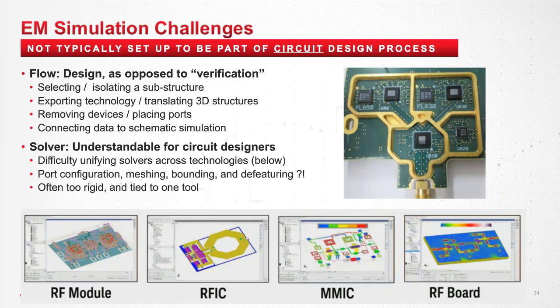Before I get to that, I wanted to also talk about the second part, the EM simulation challenges. If you look at a high level, the biggest challenge is that EM simulations aren't typically set up to be part of the circuit design process. Normally you're designing your circuit, doing interstage matching at the chip level. Maybe you're doing EM simulation on a chip, but when that thing goes off into the package, that's another design flow, and the chip is complete. Now we put it in the package, now we design the package, now we EM the whole package. Now that's complete. Now we put it on a board.